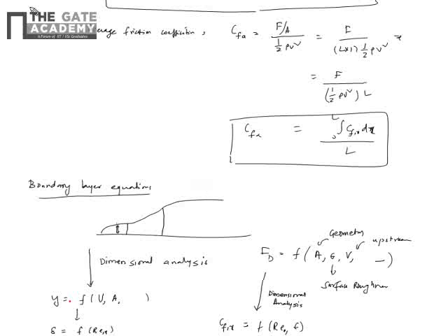So let's write down the expressions. For laminar flow, neglecting surface roughness and all that, the boundary layer thickness varies as 4.91 x over Re_x to the half, on a flat plate. These are the equations. If you take flow over a pipe or flow inside a pipe, internal flow or external flow, it will all vary.